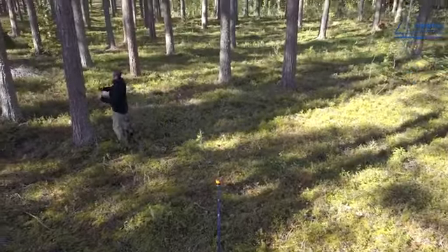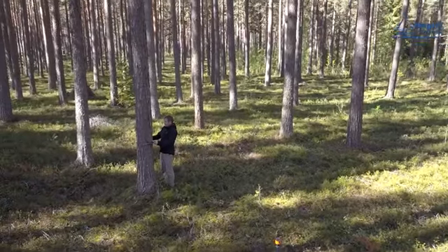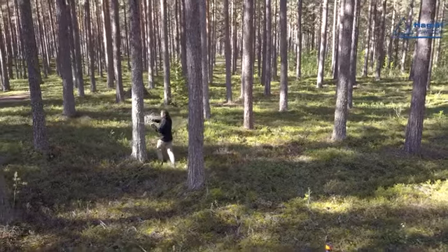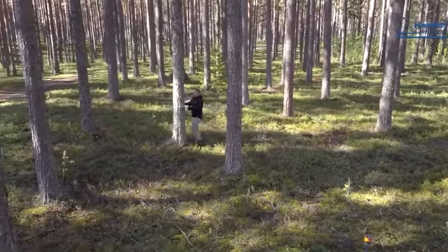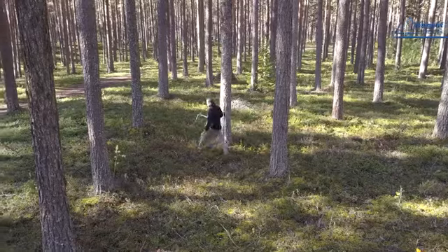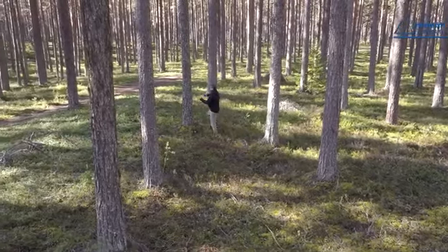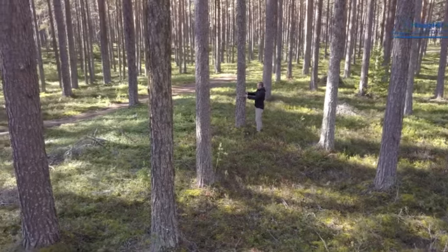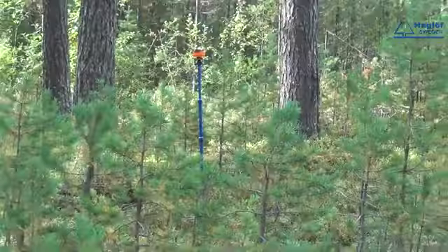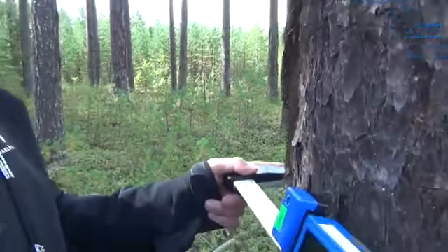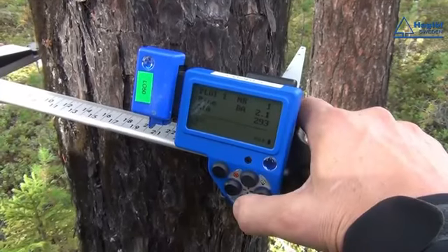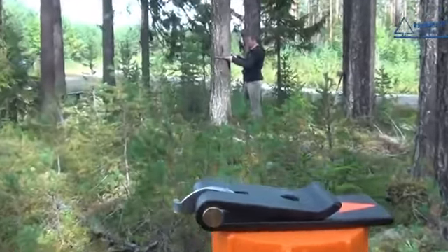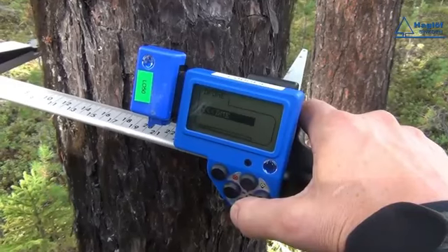Then he measures and registers tree species and diameter of all trees in the plot, within a radius of 10 meters. To avoid measuring trees outside of the plot of 10 meters, the radius is measured with the DP2 module, DME GPS. The module measures with high accuracy from the center of the tree to the center of the plot.